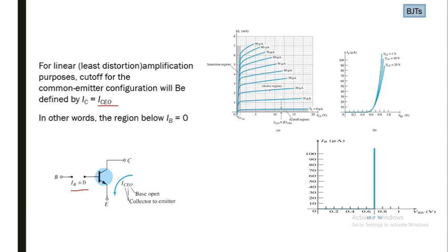We have shown the graph here. Now if we want to approximate these three curves to a single curve, you can get an approximation with this straight line, which actually ignores the resistance and ignores this knee value. So you can easily derive the relation that VBE is equal to 0.7 volt.